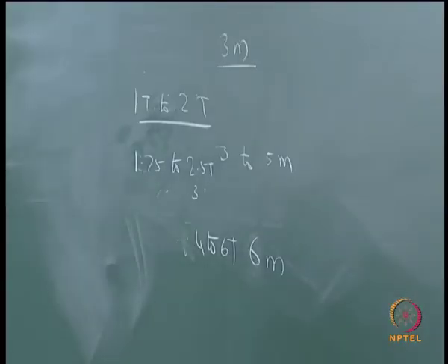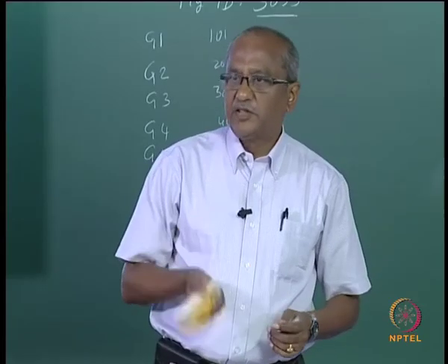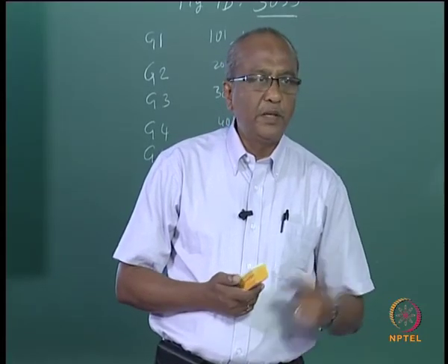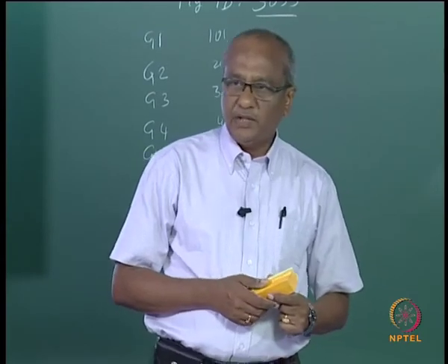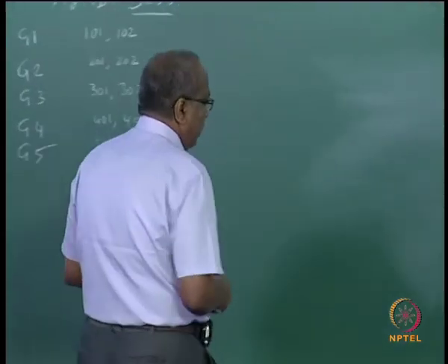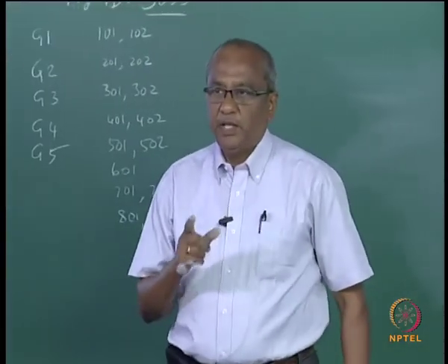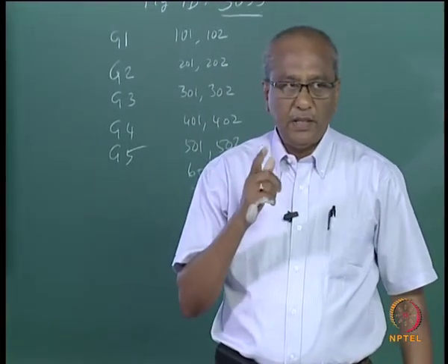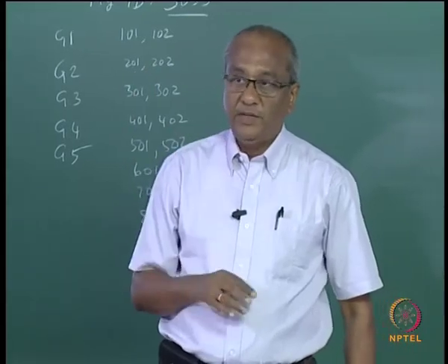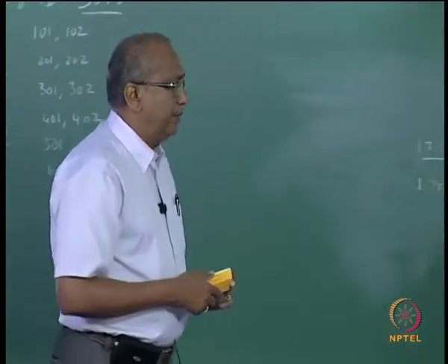So these are all approximate guidelines, but you need to calculate using the Hudson's formula or the Van der Meer's formula to calculate the weight of the stone. Mind you that fixing the wave height is extremely important. You have to take utmost care in finalizing the design wave height for the breakwater.